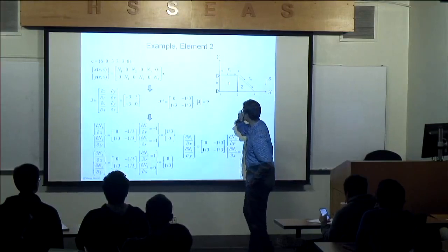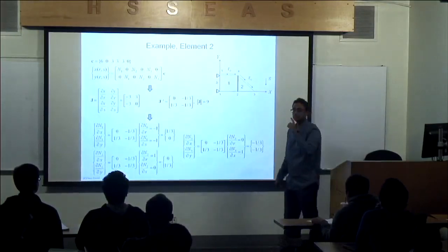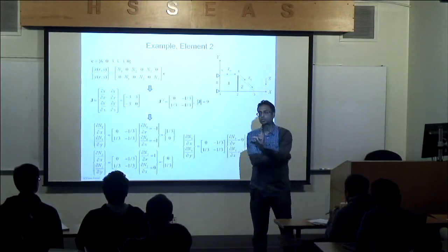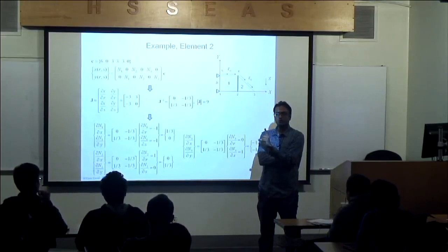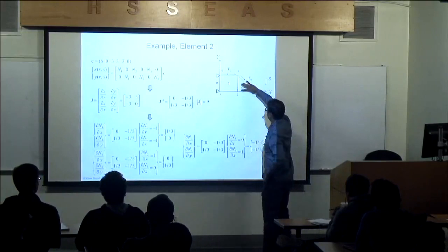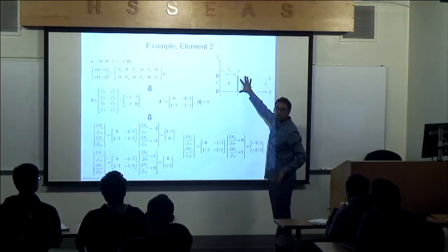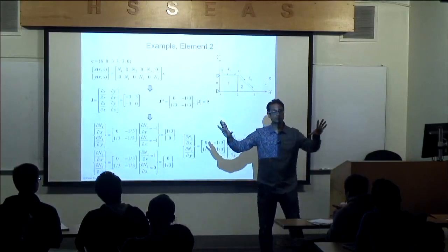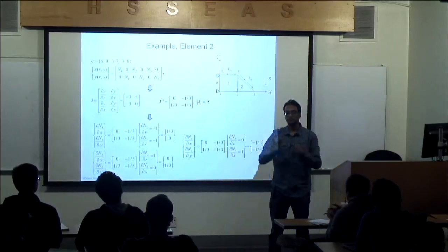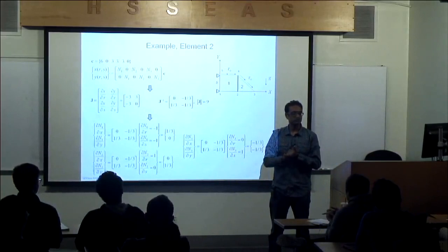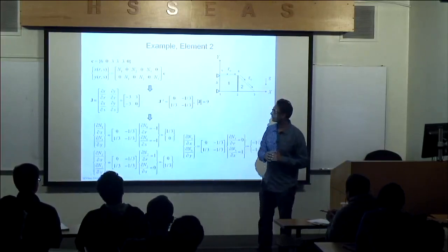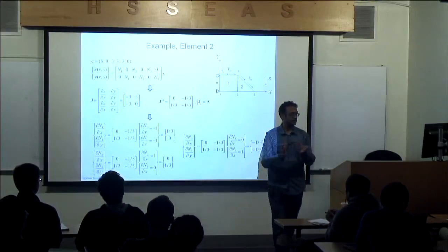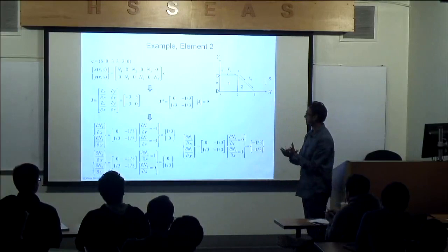Okay, 9. That's actually correct, because if you look at the standard triangular element, what is the area? 1/2. What is the area of this triangle? 3 by 3, 9, divided by 2. So I'm mapping a 9/2 to 1/2. So the mapping is basically 9, the ratio of the two. Make sense? I went from an area of 9/2 to an area of 1/2. So the ratio is basically the Jacobian. It's scaling in this case. In other cases where the elements are highly distorted, it's not going to scale that nicely, right?